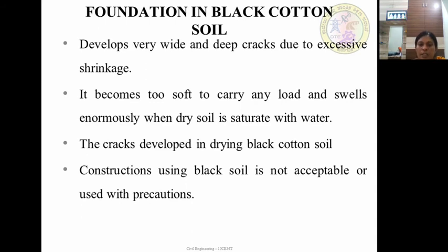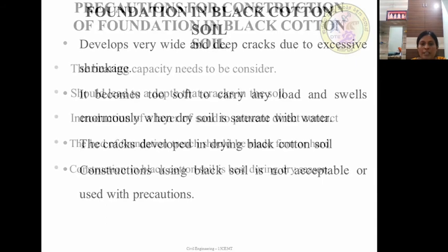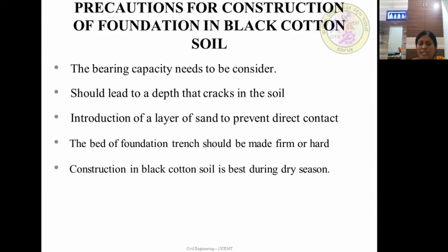Construction on black cotton soil is not acceptable unless precautions are taken to avoid the considerable effect of seasonal moisture change in expansive soil, such as reaching hard strata and taking foundations below scour level.